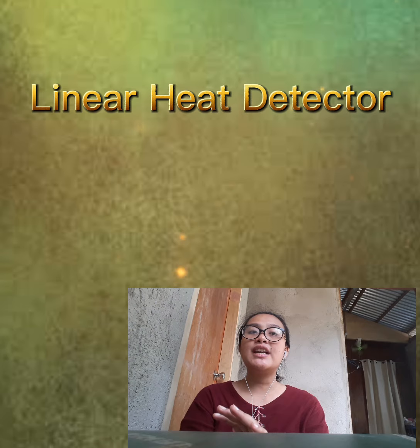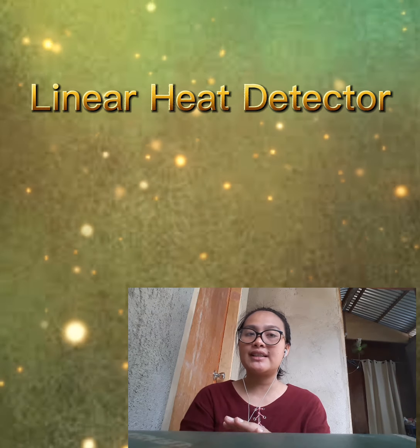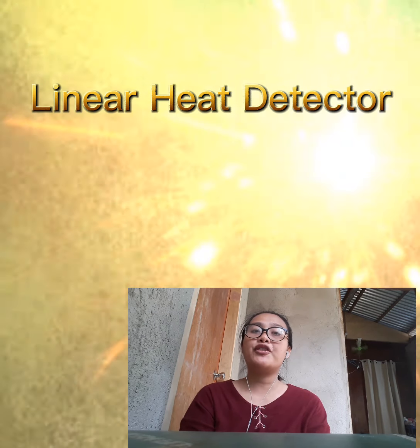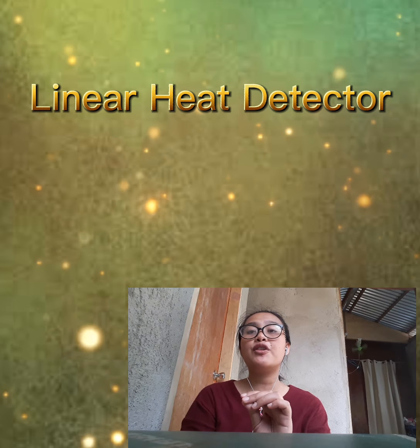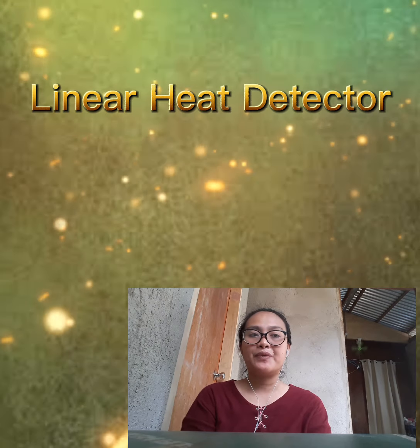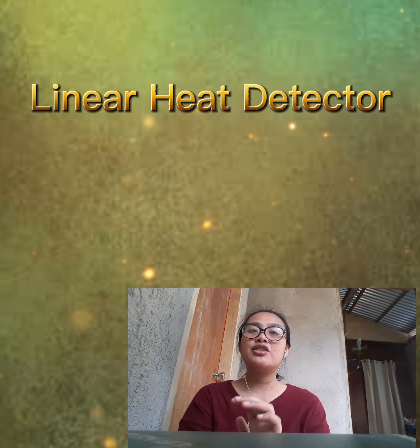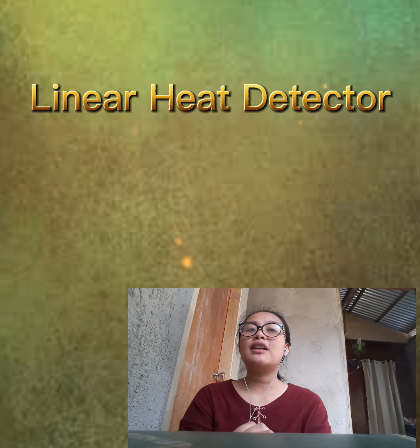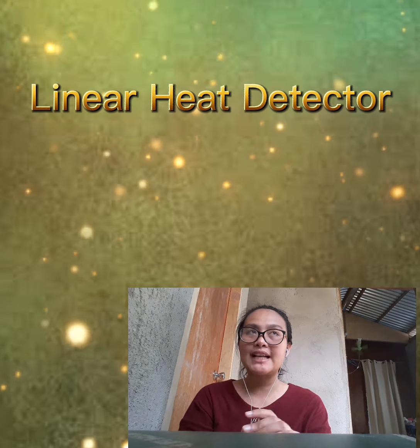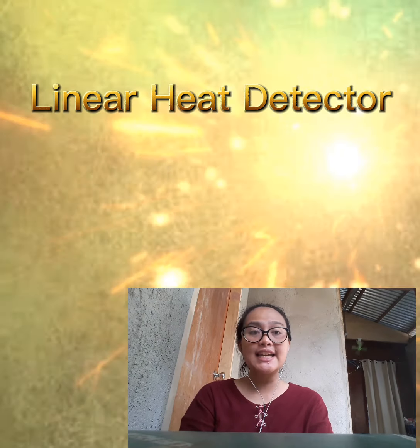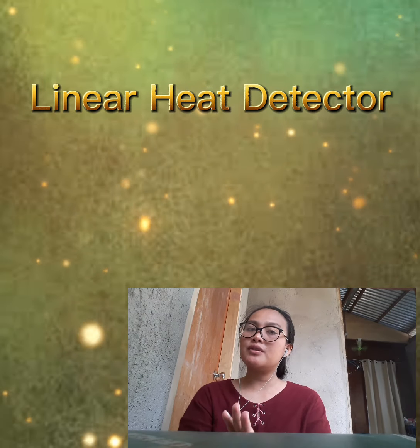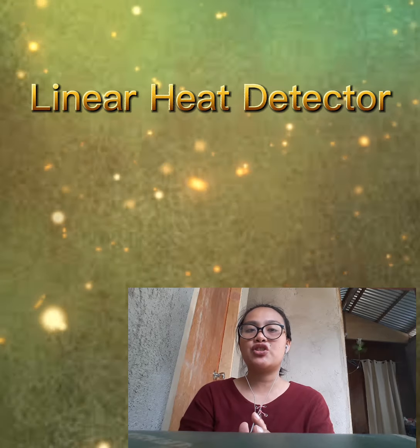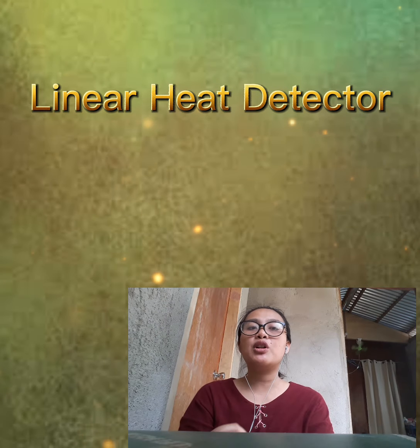Second, the linear heat detector cable and monitoring system shall be suitable for operation on a normal 24 volt DC supply. Third, the alarm condition shall be latched at the control unit with the fault indication from the gas panel. And lastly, it shall provide outputs for fault and alarm conditions which are compatible with the main fire gas panel.